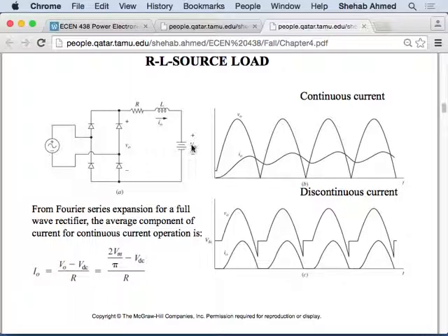Until the point where the DC source intersects the AC source again, and I'm putting a positive voltage across the output branch, which means at some point the voltage across the inductor will become positive again, right? In that case, I will have the continuous current.